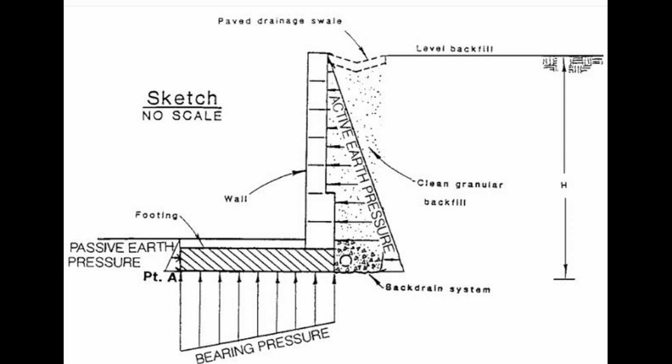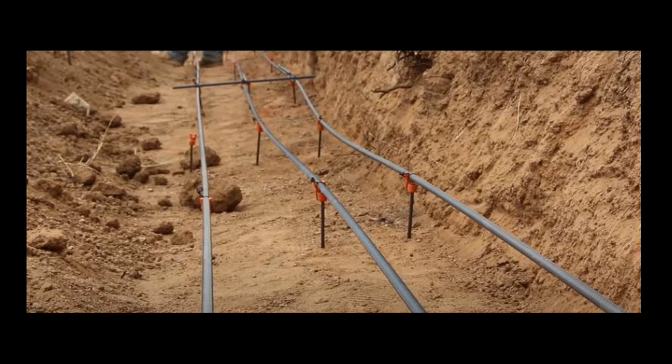of cover for reinforcement, which includes top and bottom mesh and stirrups, it helps to stabilize the passive earth pressure of soil and transfer the load to the ground. You can see on the screen as well. From the viewpoint of engineering design, a minimum cover for reinforcement, horizontal for footing and vertical reinforcement for slab wall, is required to be 40 mm.